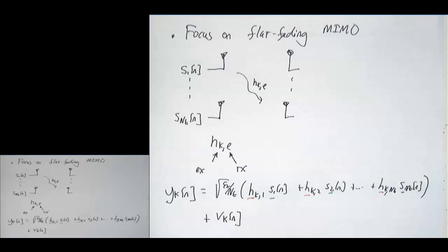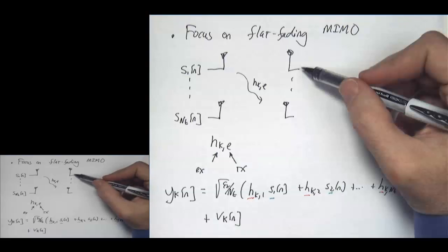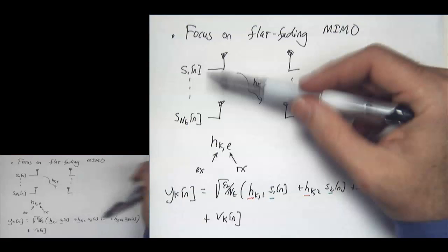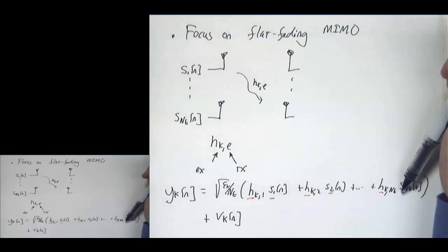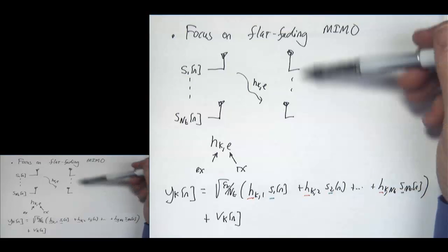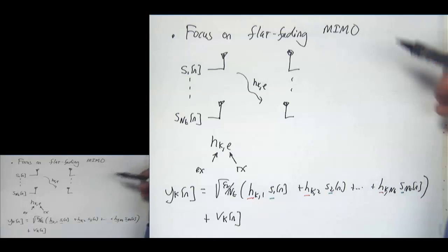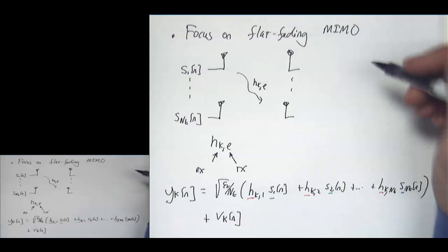And so the tricky part with spatial multiplexing here is that each receiver sees a linear combination of all of the transmitted symbols. Now what we're hoping, to make this work, is that if each receiver sees a slightly different linear combination, then maybe we'll have enough differences in the observations to put the original signal back together. So that's kind of intuitively the idea.